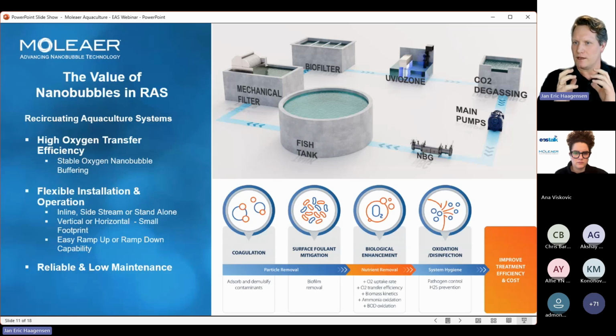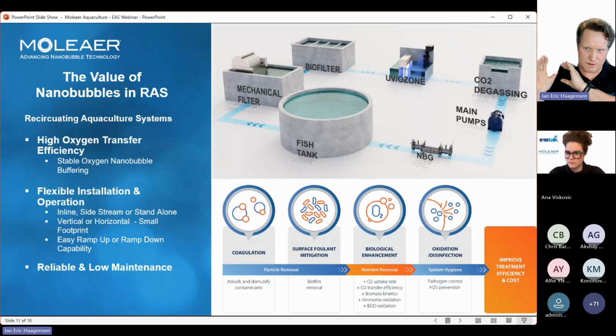Nanobubbles have an internal pressure of over 400 psi, essentially inflating it like a balloon, creating a hard surface around the nanobubble. And this has a hard shell, and under velocity inside pipes, this has a scouring effect, a cleaning effect. And this is ripping loose biofilm to the solution, suspended in the solution, so that it can go to treatment.